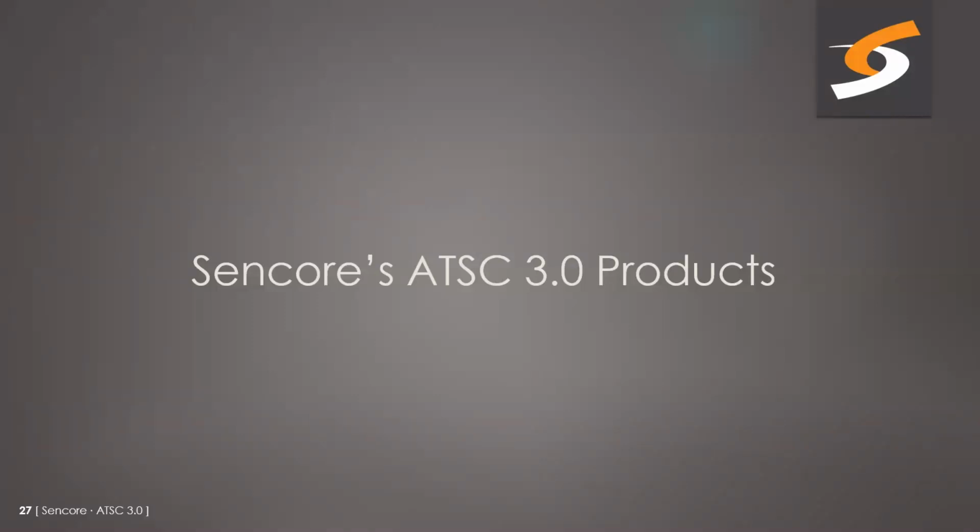Yeah, so the next one is a question around how ATSC 3.0 will interact with the uncompressed side, so doing a decode and also the transcode. The question is, is the ANC data applied as the SMPTE DID/SDID type format, or is the encoded version passed in a different way? So does it change any of the DIDs and SDIDs and how that's being laid out?